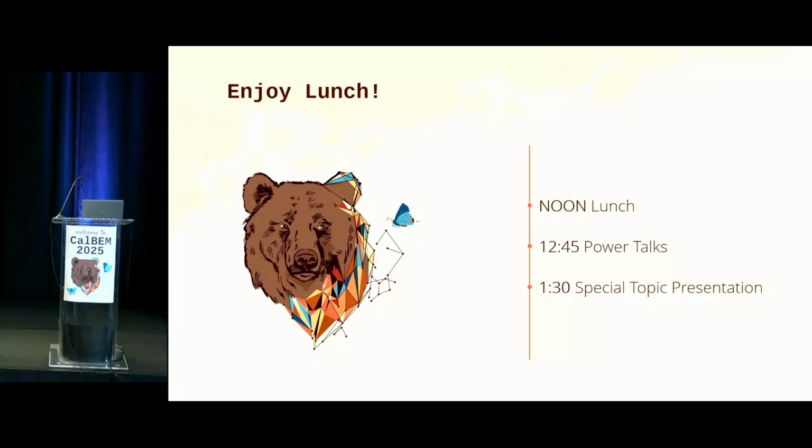I mean, if you want to, you can always model it the way you want to model it. But for compliance, we have to ensure that the hot water load is met, right? And so in the compliance software for residential, even if you were to choose efficiency mode, and you're not meeting the desired temperatures, the compliance software will add a penalty electric resistance to bring it up to temperature.